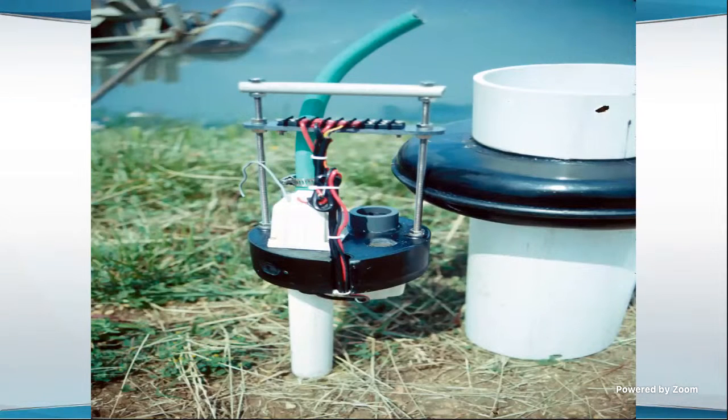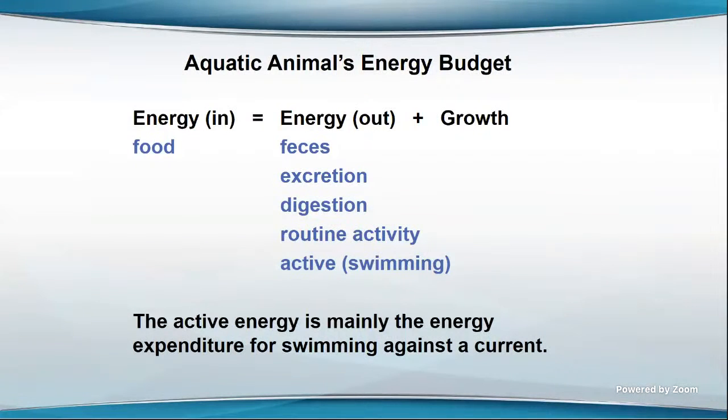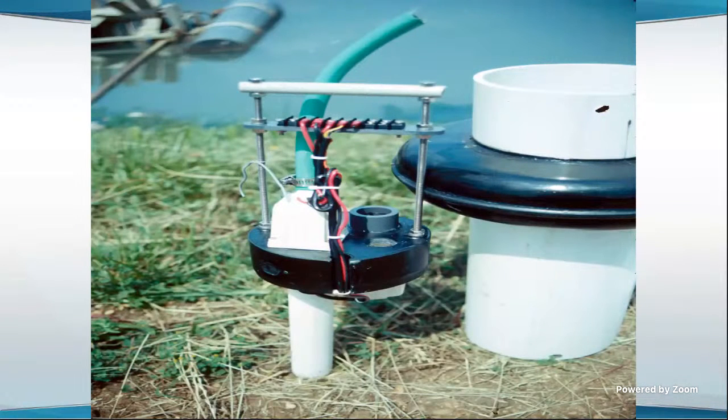Now they make devices that you can put into the water that monitor the oxygen concentration, and they'll send a signal back to either start or stop the aerator. You program in what oxygen concentration you want the aerator to come on, and at what oxygen concentration you want it to go off. You can manage the aerator through this automatic monitoring system to prevent wasting electricity on aeration. So with aeration, you need an efficient aerator.